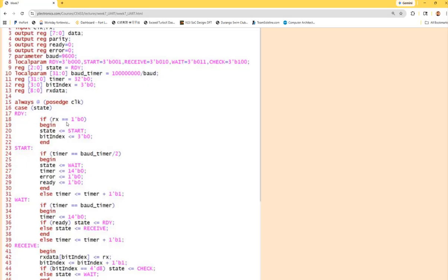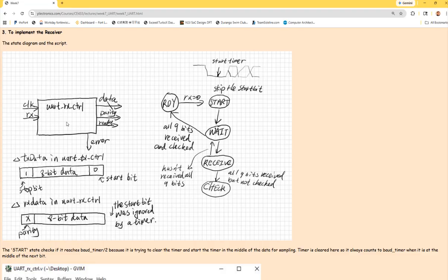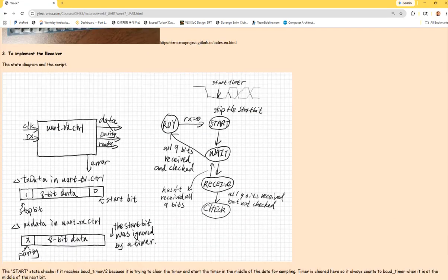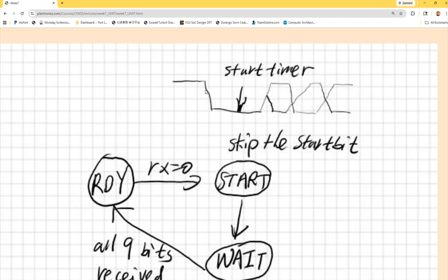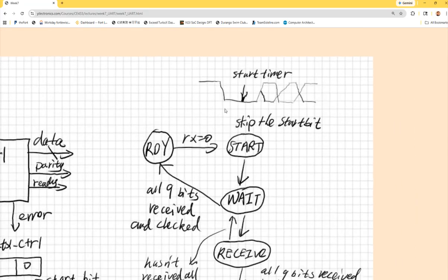So Rx is shorted to the Tx of the transmitter. So whenever Tx pulls it down, right? So you see the timing sequence over here. This is controlled by the Tx. So the Tx is sending and the receiver is just passively receiving, right? It's not controlling, pulling up and down the transmission line. So it's basically just being put down by the Tx. Okay. And that's the starting bit, right? The starting bit is a 0, logic 0.